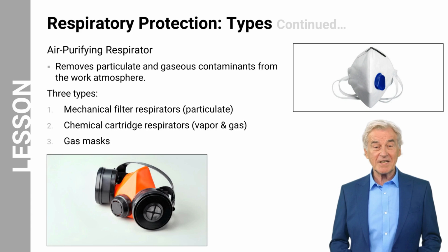On the other hand, air-purifying respirators remove particulate and gaseous contaminants from the work atmosphere. There are 3 types of air-purifying respirators. These are mechanical filter respirators, chemical cartridge respirators, and gas masks. We will discuss these types in detail in the upcoming slides.